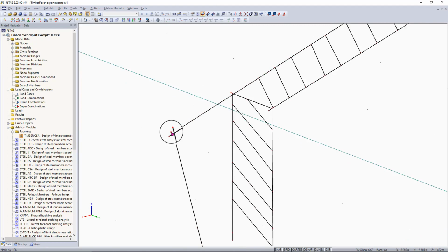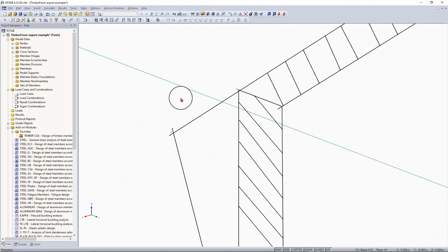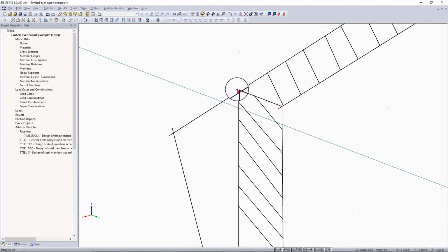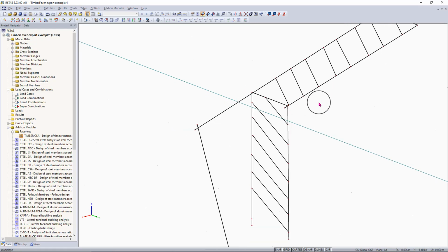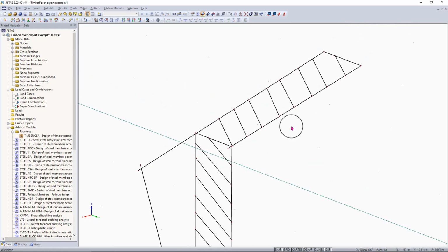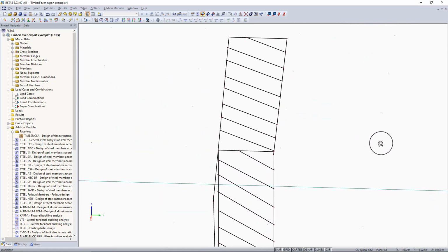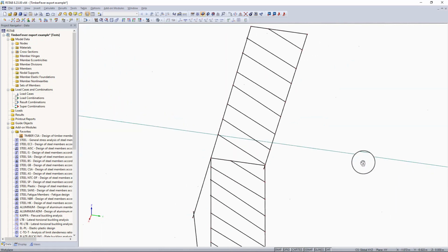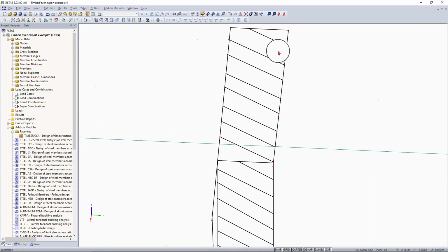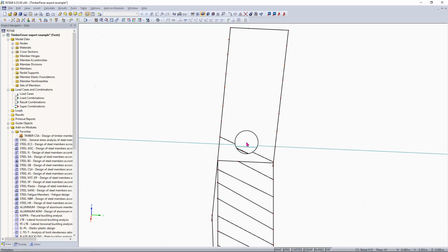We can also go through and click on these floating nodes that we don't need anymore, and we can simply get rid of those. And now you'll see that we're left with this section here. The next thing we can do is simply delete these lines right here by dragging from right to left, and then we can hit delete.